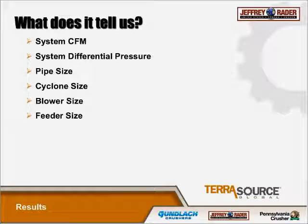If the system's designed too small, obviously it won't convey the material properly or at all. You have material just sort of slugging down the pipe as pressure builds up behind it, then shoots forward a little bit more and pressure builds up, and it's not efficient at all, with increased wear. And then a system designed too large is also a problem, because you don't want to waste power, and you could have too high a velocity and the air just runs over the material. So in either case, it's very important to define a set of specifications and stick to them.